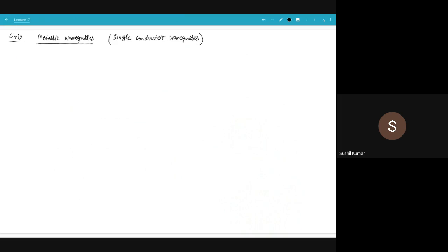I want to talk a little bit about their limitations. They have size limitations for the frequency you want to choose. For example, these don't work at lower frequencies. So what lower frequencies and what's the limitation? Well, you already saw the limitation. We derived cutoff frequencies, right? And there is a certain cutoff frequency, the lowest for our TE10.